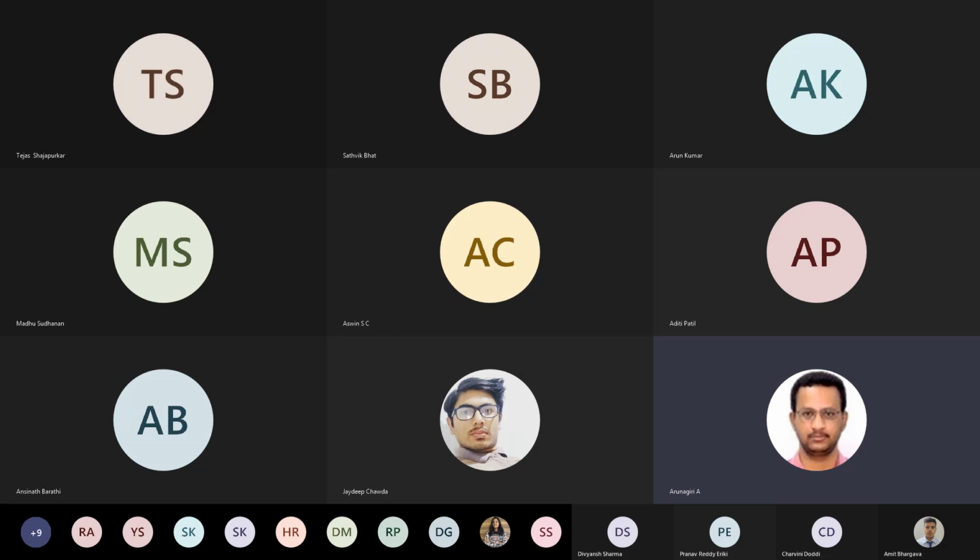So they looked into the reasons and identified that stream analysis is a must, especially on the shell side, because there were so many clearances: tube hole to tubes, shell to bundle, and pass partition plates.